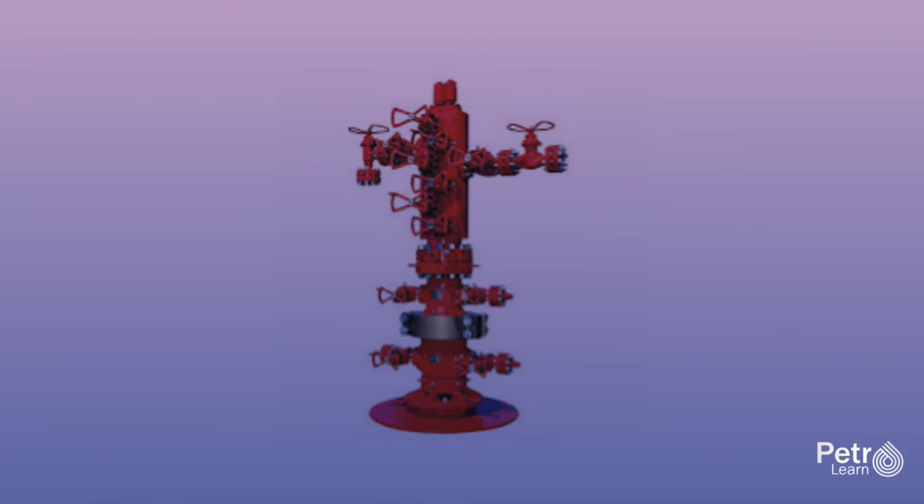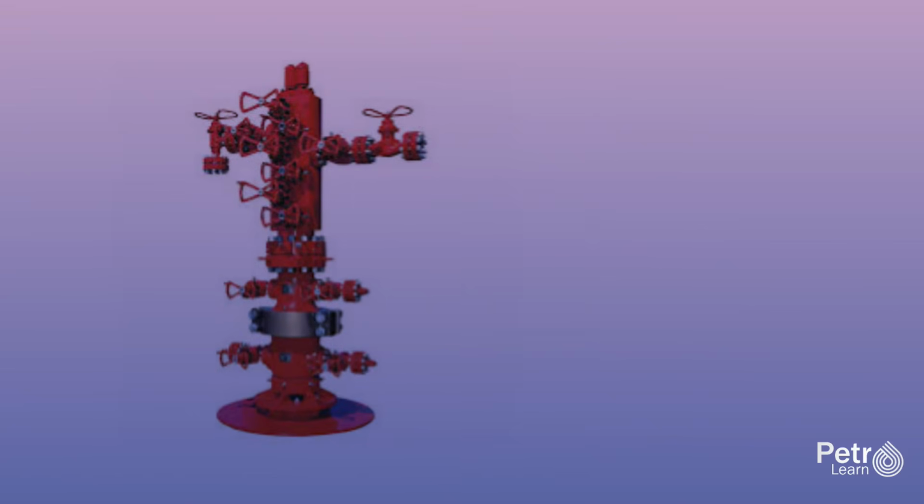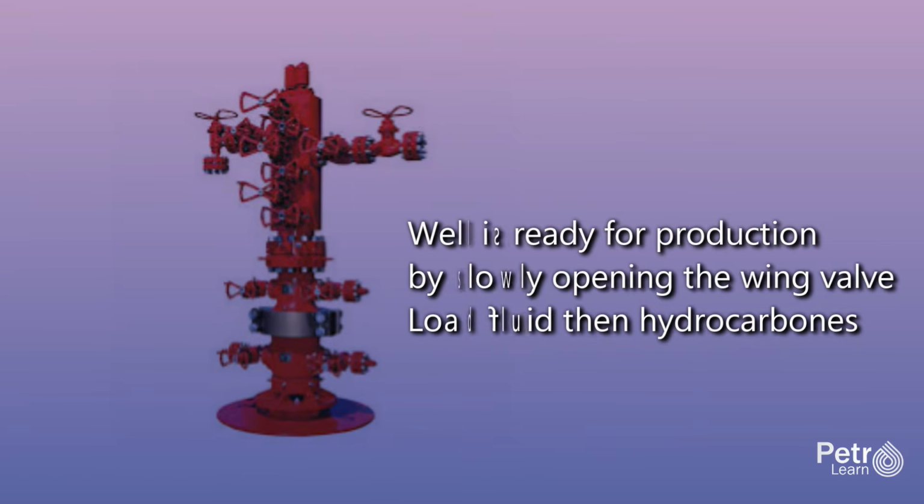With the tubing and Christmas tree installed, the well is ready to be flowed for the first time. Initial flow testing establishes the well's production characteristics. The well may flow naturally if reservoir pressure is high enough to overcome the weight of the fluid column in the tubing and the pressure in the flow line. For our 12,000-foot well with typical reservoir pressure at the depth, natural flow is likely, at least initially.